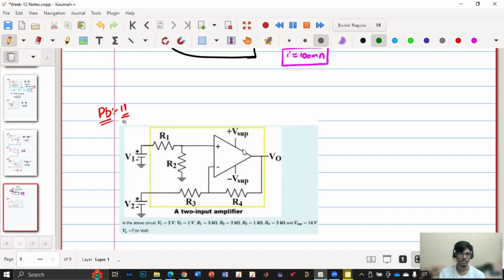Yes. Actually, the objective of that circuit is to check the overdamped, underdamped, and critically damped cases. I have made a video on that. For the overdamped case, we need to provide higher resistance. As a part of the experiment, I performed that experiment. While looking back at the video, my professor and I observed that it is getting loaded, but as the resistance is increased, it is not loaded because the current drawn is less. So that's why it is a proper step. Else it is not a proper step.